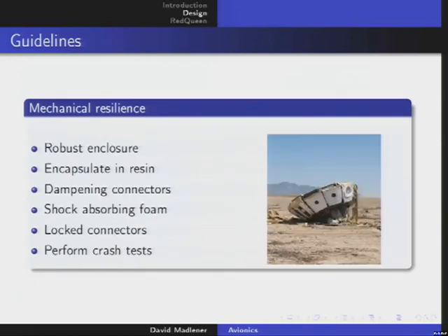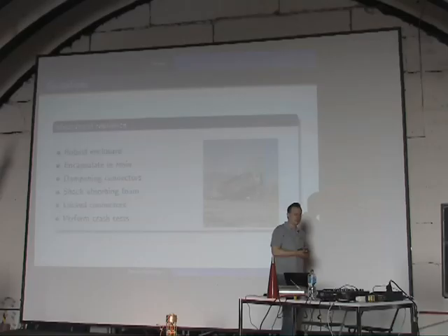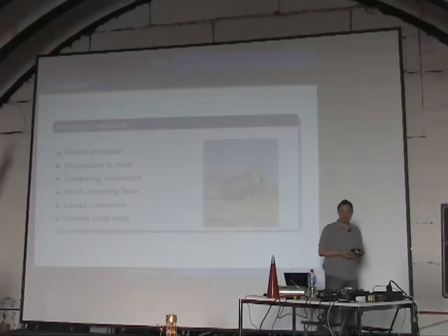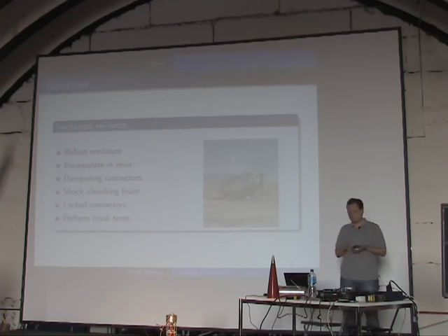So, and perform crash tests. To really believe in your system, you really have to test them once, let them fall from, not that high, you don't want to destroy it completely maybe, but let it fall from, let's say, 1 meter or so, and look if it's still working. If something is going wrong, then you know there's some connector or some problem on the PCB, and you have to look for that. And this is long, long, tedious work.